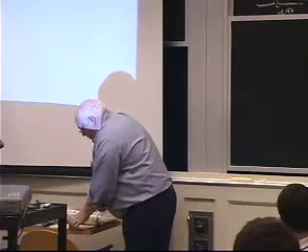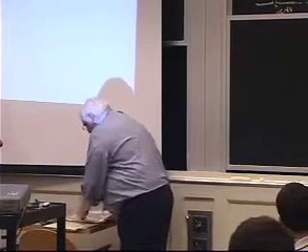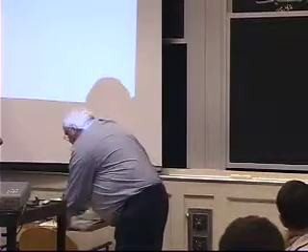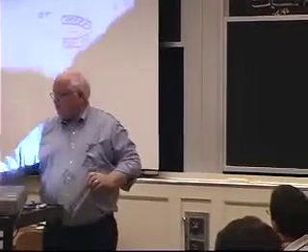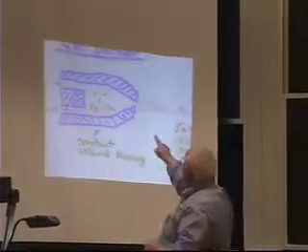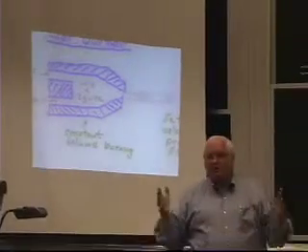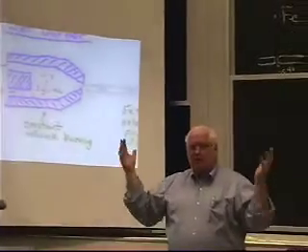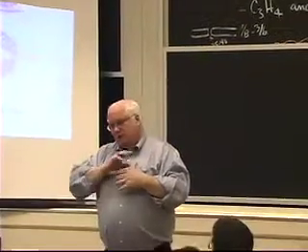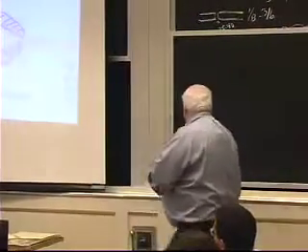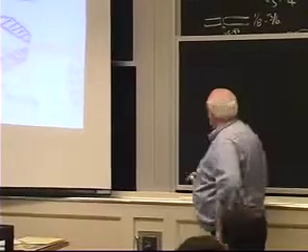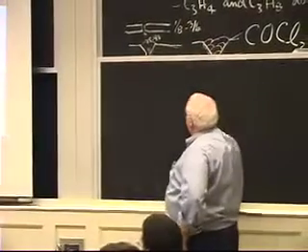in the air at 1 atmosphere. So here we have a diffuse flame. Here we have a pre-mixed burner, constant pressure burning outside in the 1 atmosphere air. But if I go to a jet burner, I actually mix and ignite in the chamber, and this stuff is coming out at a much higher velocity because I got all this PDV work. Okay, it increased in temperature from the ignition of the gas, and it comes shooting out at a couple of thousand degrees or 3,000 degrees, depending on whether it's air or pure oxygen.